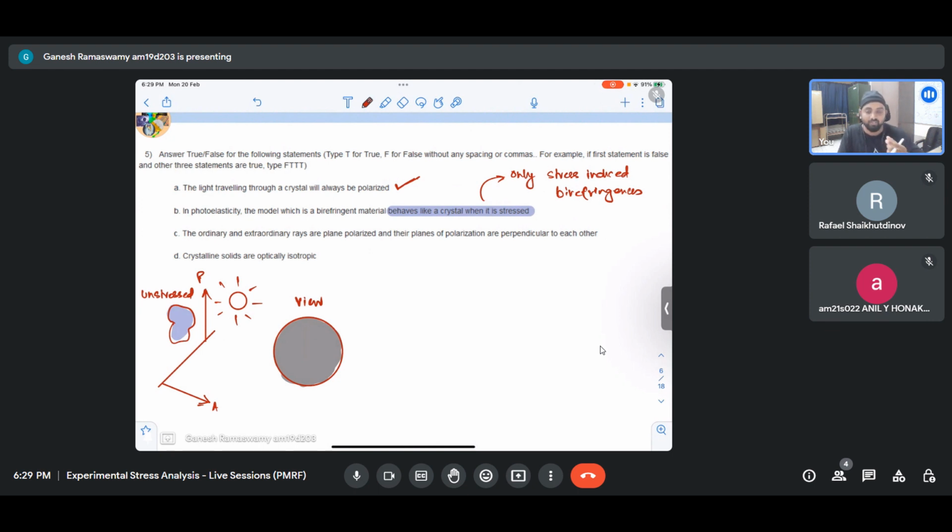If we were to take some material which has not been used for a while and keep it there, we'll be able to see some colors around the boundary. We'll be able to see sort of a halo. Why that happens is because of water moisture absorption. Materials like epoxy have a moisture absorption issue.